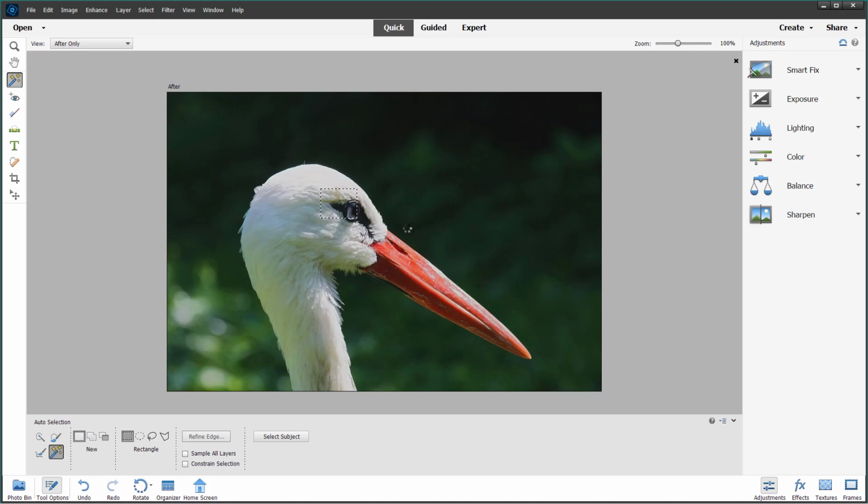Just like this, you can select it just by clicking and dragging a certain part right here, and that will be selected. So the contrasting areas are selected once you click on this. Then you can go over here and add to the selection. So if you want to add in more areas, you can select them over here as well, or you can deselect this out over here just like this as well. So you can use the deselection or adding in.